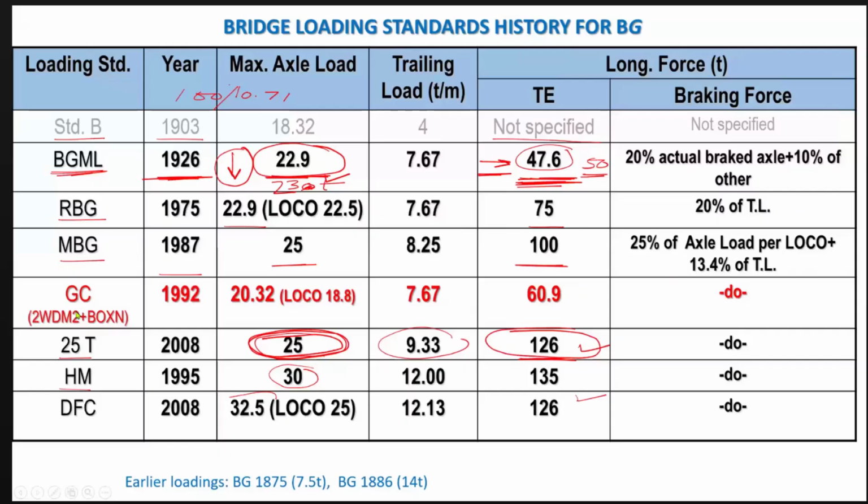Gauge conversion loading, sir, when MG lines were converted to broad gauge. Yes. Thank you very much. Basically, this loading is not shown in our bridge rules, and many of our new engineers don't know about this loading, and they are clearing their bridges. They are not rating with this loading.